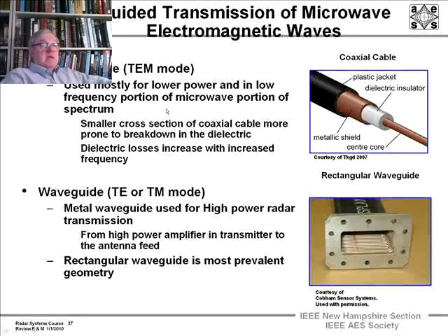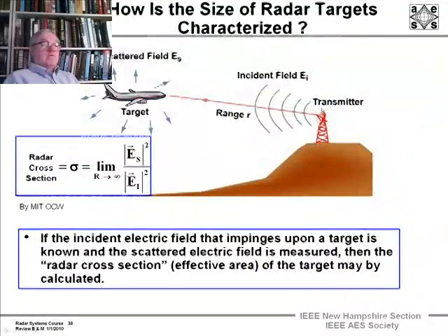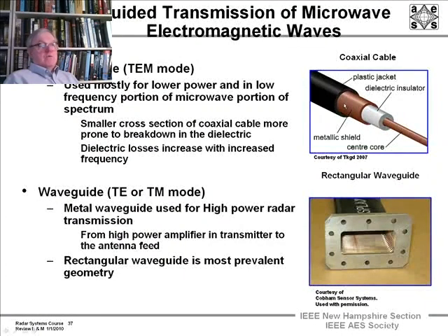But it can bend easily. You see you've got a center core of conductor and a dielectric insulator which separates the outer coaxial conductor, which is a magnetic shield, usually sheathed back and forth, and then over it a plastic jacket that would protect this coaxial waveguide, literally, with a dielectric insulator from the elements.